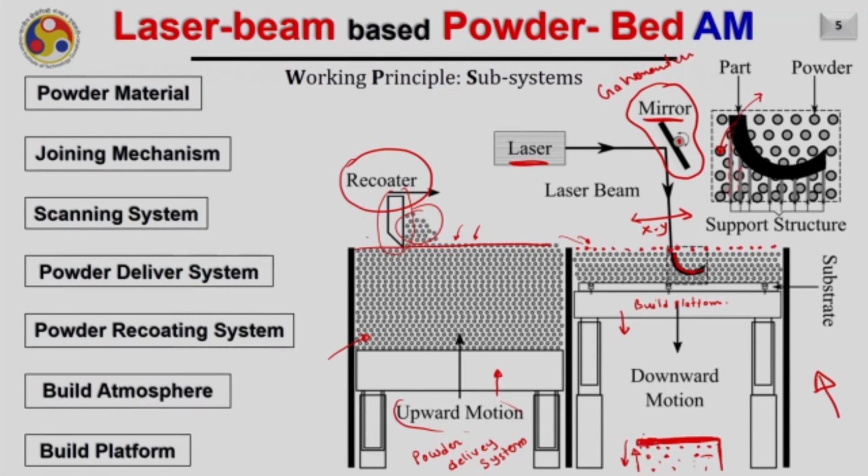So, that is not our worry here, but as it is a tiny layer of around 40 micron, if it is a very large overhang, then it may happen that after solidification this layer may warp like this, and it is due to the residual stresses in the layer.